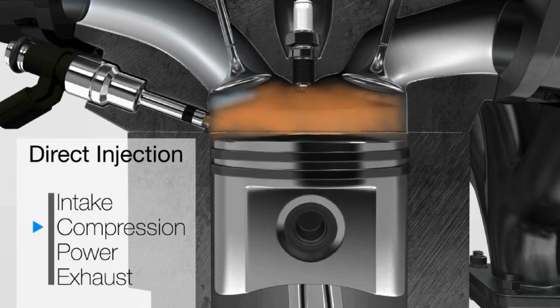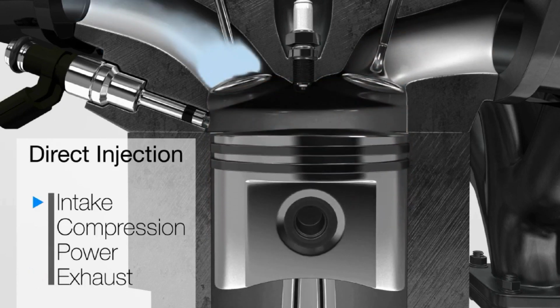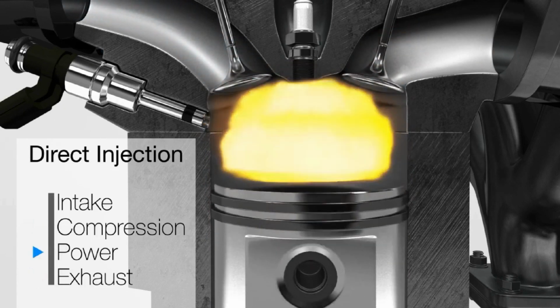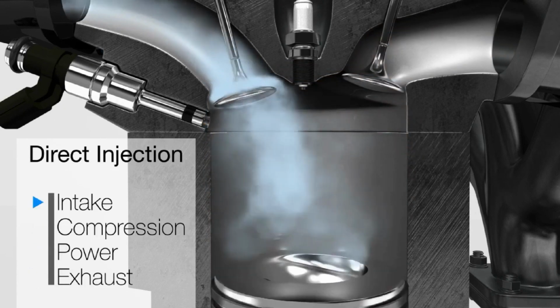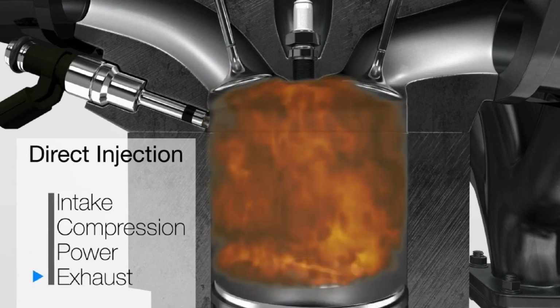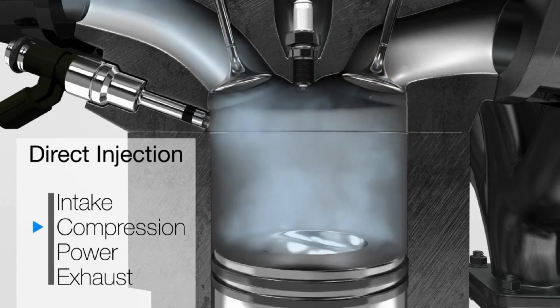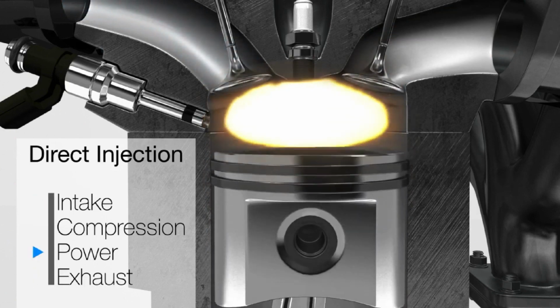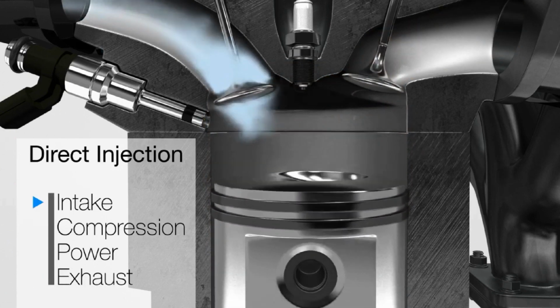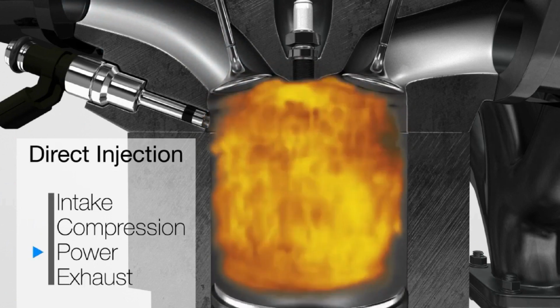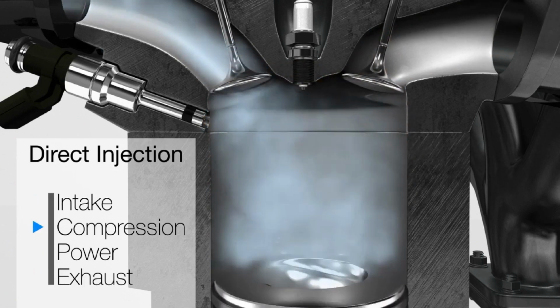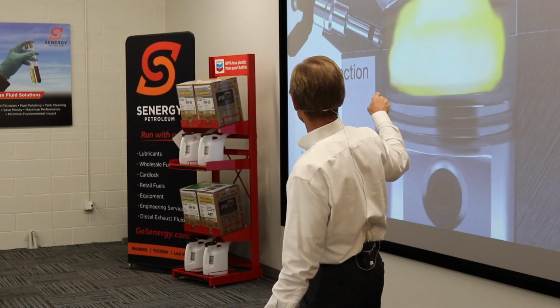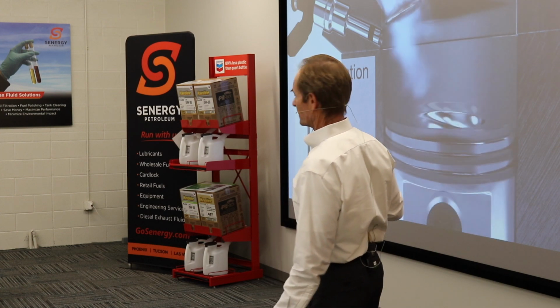All right, and then carburetors were replaced by throttle body injection for a year or two, where, again, up here, you were injecting fuel into the airstream, which would come on down. A vast improvement on throttle body injection was port fuel injection. So here in the intake port, you'd have an injector, up ahead of the valve that was injecting your air-fuel mixture, and the air-fuel mixture going in.